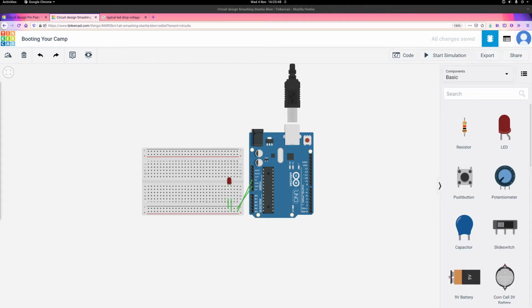So we want to calculate what value of resistor would give us that current. Okay, we'll ask it in parts. So the first question is, how much voltage does the resistor need to drop according to Kirchhoff's voltage law? So we have a 5 volt source, 1.7 is lost on the LED. What remaining voltage is lost? Yes, fantastic. I would agree, 3.3.